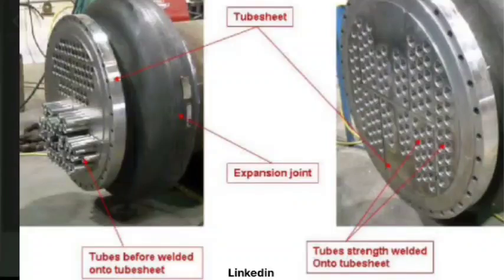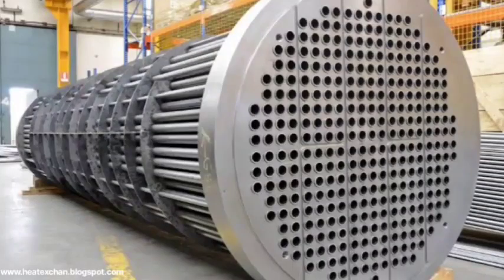Okay, Abhishek, you got the answer? Okay. And then who defines whether it should be full strength or partial strength? See, as I told you, this comes only in fixed tube sheet configurations. How much load will come because of the thermal expansion? You should design at least for that. But some clients say no, you design for full. So this is normally decided by the client.